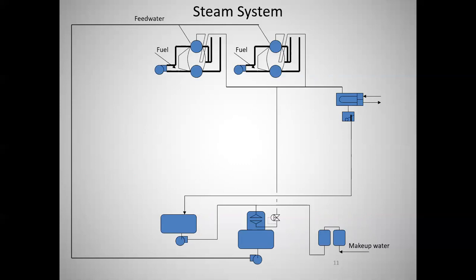This is showing drums, those little circles. That top circle in blue is the main steam drum, and the bottom is what we call the mud drum. Because guess what? Sediment and stuff tends to settle to the bottom. So these are reservoirs of water, and they have tubes.